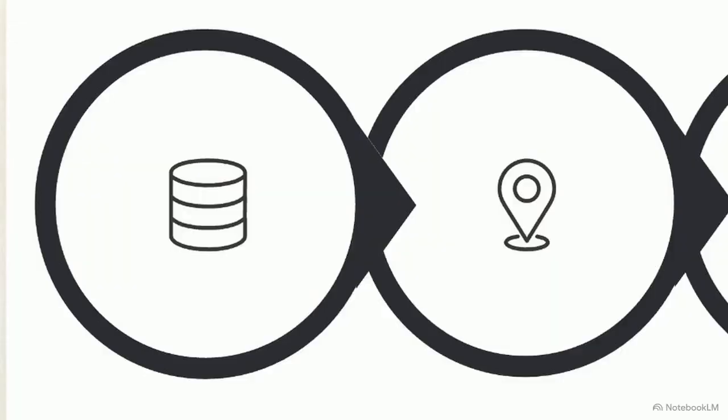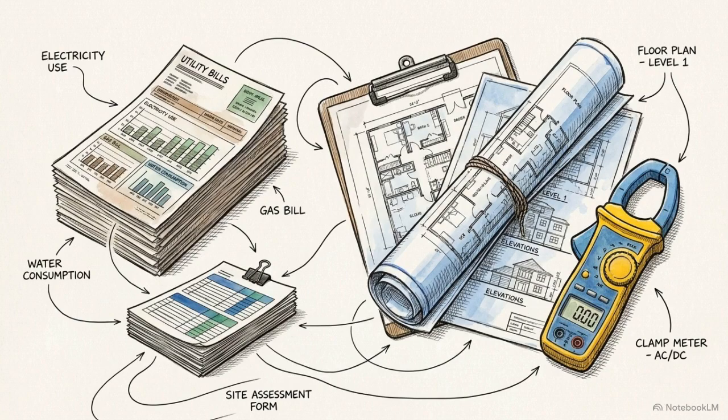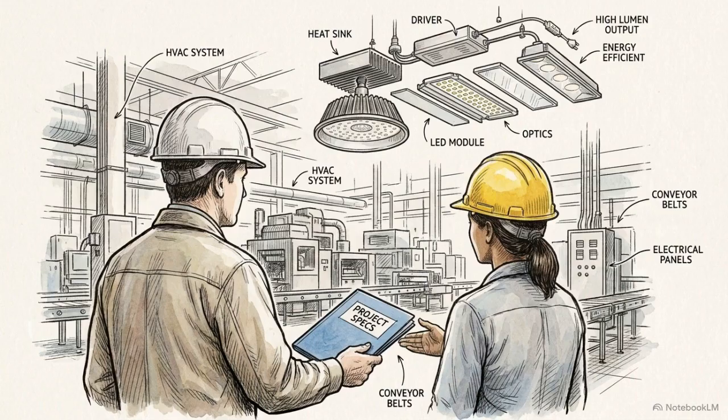To calculate where and how much energy is being consumed, the audit must follow a structured three-step approach: desktop data collection, field data collection, and the cross-checking of load demand data. Before beginning, gather the prerequisites: 12 months of utility bills, building architectural and mechanical drawings, standardized data collection forms, and specialized measurement tools. Mastering this sequence allows you to move past theoretical estimates and identify the specific energy conservation measures that actually deliver a return on investment.